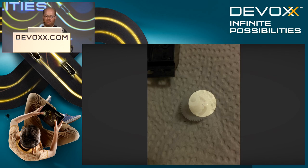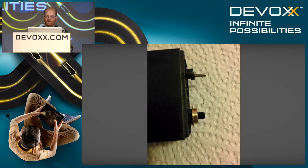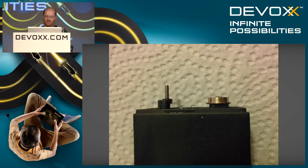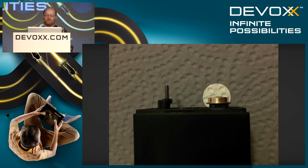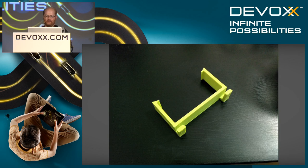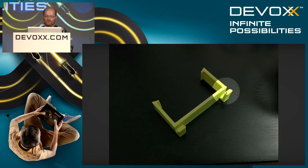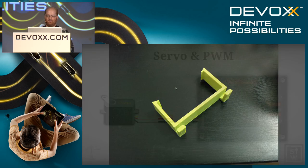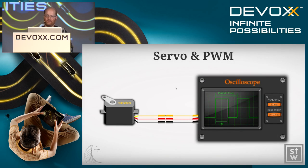And you just take that apart, just use a knife or something, and then you have to actually push in this resistor, so just push it out of the way and make sure it's in the middle position, roughly, so the servo will stop if you go to the middle position, and then you can control it to move backwards and forwards. So yeah, and this is the servo mount that you use these here to attach to the main frame, and then you put in the servo.